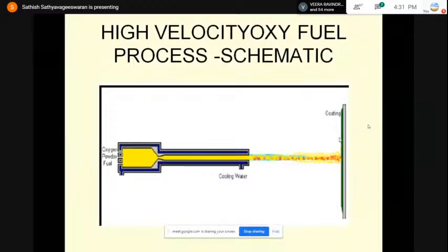So you can see that the entire plasma spraying equipment is enclosed in a vacuum environment. Thereby, if you are measuring the porosity after performing coating, definitely your porosity will be reduced to the maximum extent. I can assure you that the porosity will be less than 5%.